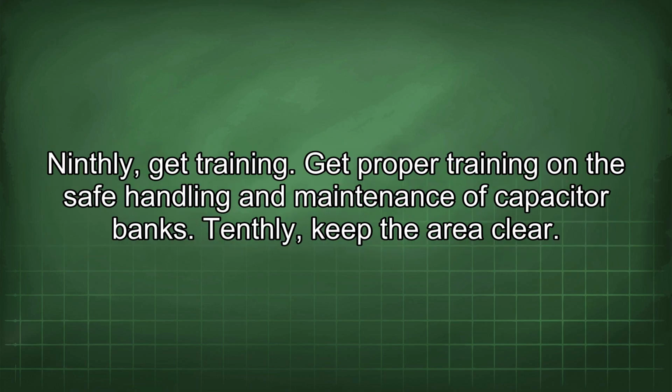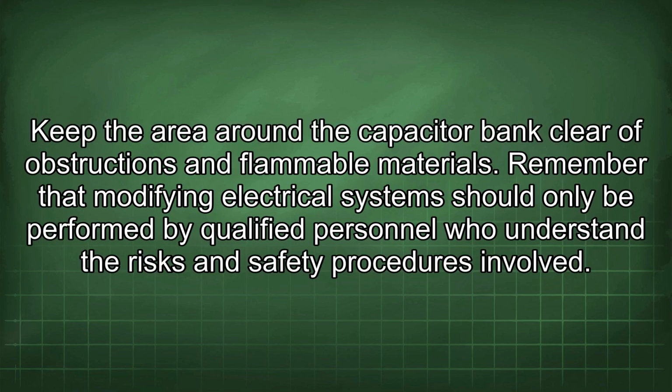Ninthly, get training. Get proper training on the safe handling and maintenance of capacitor banks. Tenthly, keep the area clear. Keep the area around the capacitor bank clear of obstructions and flammable materials.